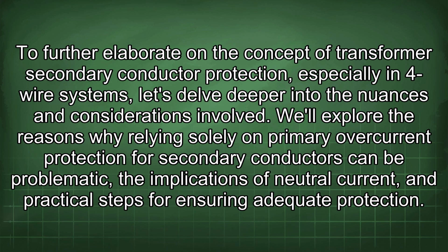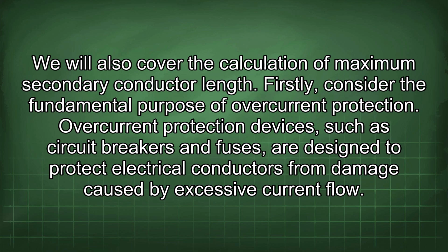To further elaborate on the concept of transformer secondary conductor protection, especially in four-wire systems, let's delve deeper into the nuances and considerations involved. We'll explore the reasons why relying solely on primary overcurrent protection for secondary conductors can be problematic, the implications of neutral current, and practical steps for ensuring adequate protection. We will also cover the calculation of maximum secondary conductor length.